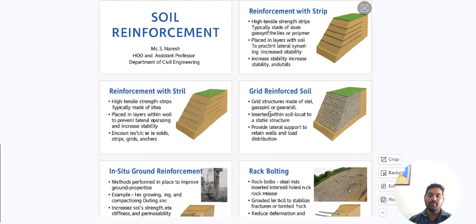So this is a problem. Maybe due to road users, or heavy vehicles, or any rainfall, it's not a problem now, but in the future it is. So if you want to prevent this problem in the future, we also need to go for rock bolting.